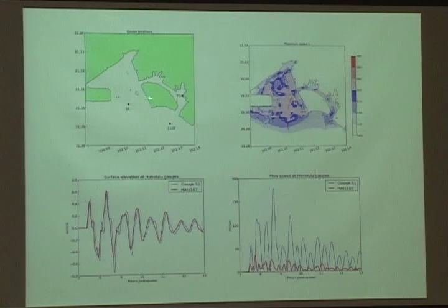And this was a study we did just to show how much variation there is between 2 points that seem to be close together on the global scale. If you look at these 2 points and you look at the surface elevation as a function of time, so these are both out of the simulation, but just looking at 2 different points, they track each other pretty well. But if you look at the maximum flow speed at these 2 points, at this gauge where it was actually measured is the red curve down here. At this gauge up here that we put in the computation, you have an order of magnitude larger velocity. This gauge we put in here was sort of in the entrance to the harbor, where you could have quite strong flows, whereas this one was out away from shore where there wasn't quite as strong a flow going into the harbor.